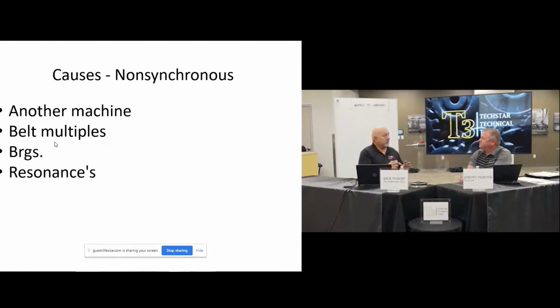And if you don't know the rollers, you can use the number of rollers times RPM times 0.4 for outer race and 0.6 for inner race. Okay. And that gets you kind of close. That's kind of the rule of thumb calculation for calculating bearing frequencies.